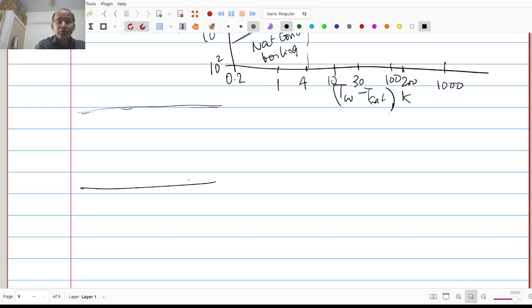There is no bubble that is formed on the surface, but the hot liquid at the surface becomes equal to the wall temperature, T wall greater than T sat, but the temperature difference is still under 4 degrees Celsius. Then the hot liquid, which is reaching temperatures greater than saturation temperature, still does not form vapor bubbles.